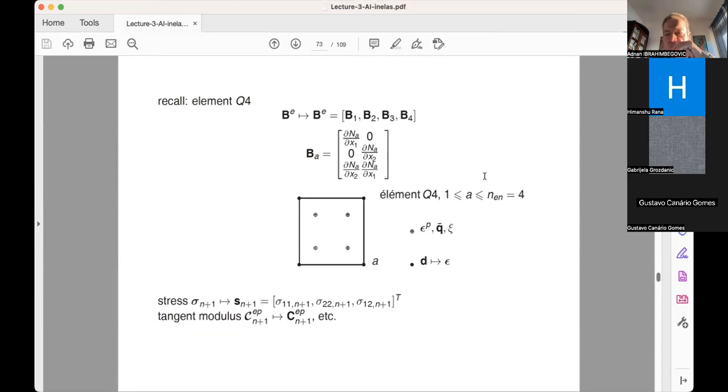Now, as I said, if you take, let's say, a 4-node element, you will have to do something special. You cannot handle plasticity with just the basic 4-node element. I'll show you with a couple of examples that this is the case. First of all, how you actually build this type of element. First, you build your total deformation field by using displacements at the nodes, and then shape functions for computing the interpolation. In particular, for the total strain, you need these B matrices. For each node A, you have derivatives of the shape function N A with respect to either x1 and x2 to compute the corresponding strain components. So this is one type of computation that we have to obtain at each and every Gauss point.